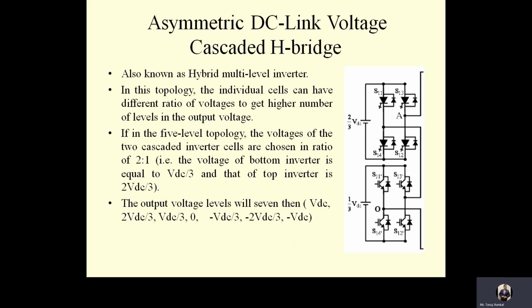Hence, the switches in the top inverter can be replaced by low frequency, high voltage GTO devices, while the bottom inverter can be normal IGBT inverters. Therefore the inverter is called a hybrid multi-level inverter.